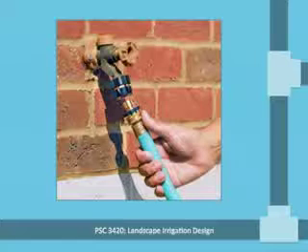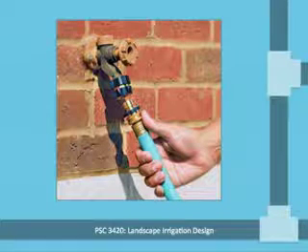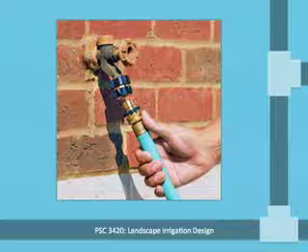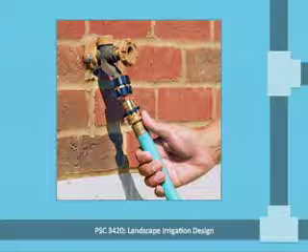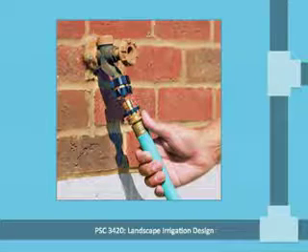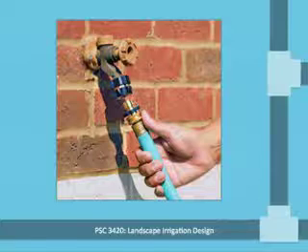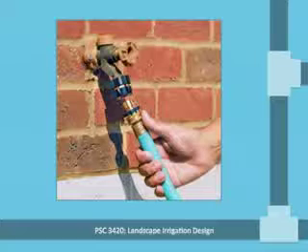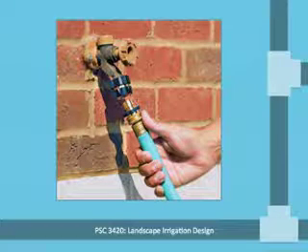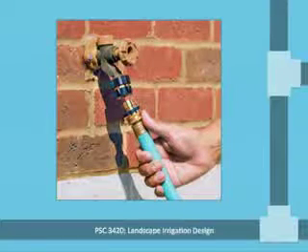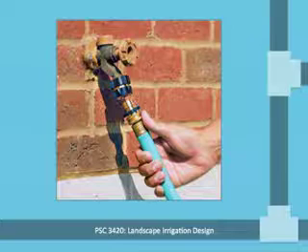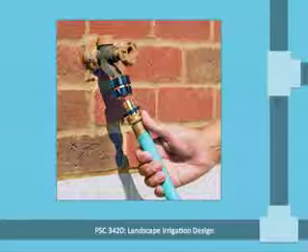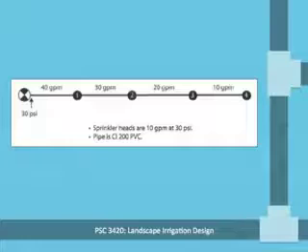And it's really important to know what the flow is for each section of pipe in an irrigation system so that you can determine friction losses and what size pipe to choose so that you have an adequate amount of pressure in the irrigation system that you design. Now we're going to talk a lot more about friction losses in the next lecture, but it plays a big role in flow, so you're going to hear me mention it a few times here as well.